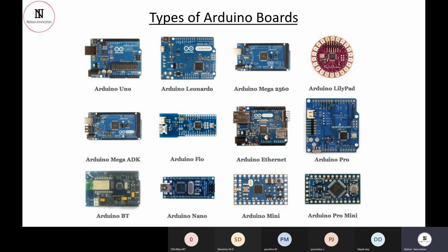If there is a space restriction, and you want the same compatibility that the Arduino Uno is giving you, then you can surely shift to Arduino Nano as well, because the processor is almost the same. There is also a very good advantage with the Arduino Nano: in Uno we have seen the analog input pins are from A0 to A5, a total of 6, but in Nano it's 8. So we have an extra advantage in the Nano as well. One is its small size, and second it has more analog pins.